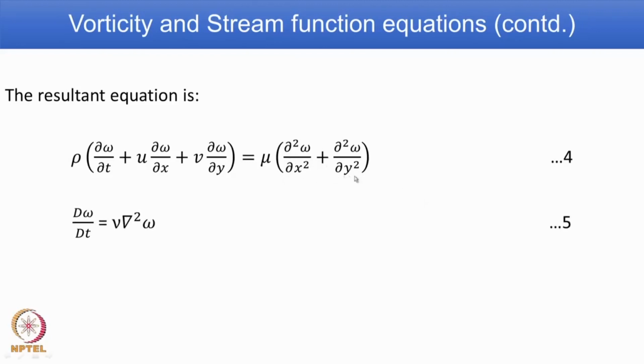So, if you look at this equation, the way the equation looks is all similar. We had a similar format for u momentum equation, except that the variable is now vorticity omega. Otherwise, you are again able to recognize this is a local and these two are convective kind of term, and if you put them together you get total derivative expressed in terms of omega.